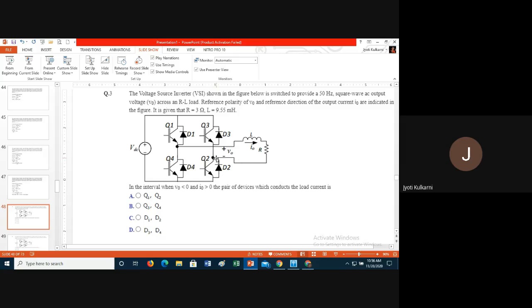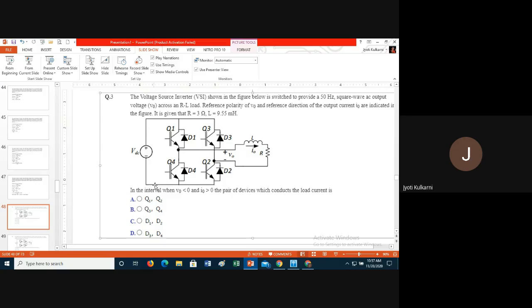And in which direction did you get the current? Let's see again. What did I get? I'm moving in the battery plate positive to negative, negative to D4, D4 to the upper dot which is now negative, from negative again L to R. See, the current direction is not changing, my current is flowing from L to R only, so I0 is still positive.